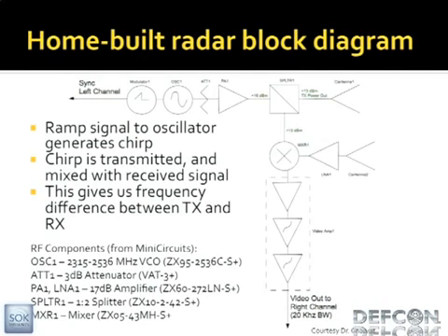I'll try to go through it and explain what's happening here. So the first thing is the thing that says modular, that little spike thing, that's the ramp generator. It's generating just a ramp in voltage, which gets fed to this thing with the curvy line called a voltage-controlled oscillator, and it does exactly what you think. The frequency of oscillation is related to the input voltage. So you send it a ramp, and it gets faster and faster, and that generates the chirp I was talking about earlier.